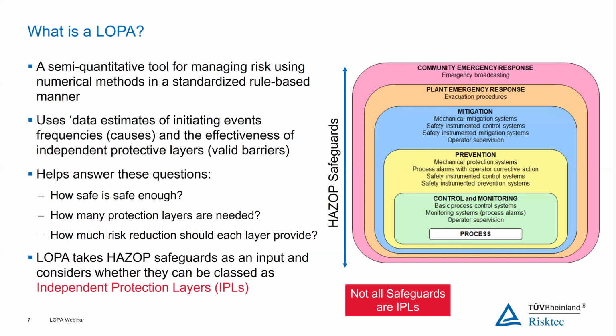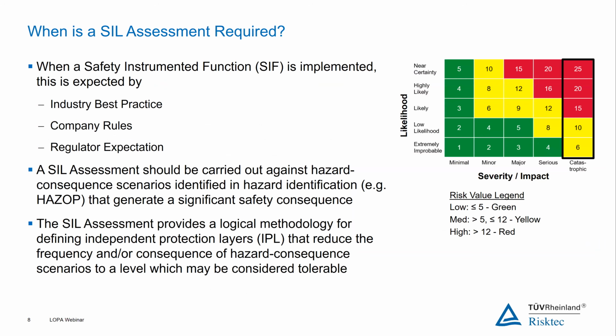So there may be things such as ignition factors for probabilities of ignition in specific areas, occupancy factors to assess the specific likelihood of fatalities or impacts to personnel, again, within specific areas or from specific systems. Even things such as weather modifiers based on prevailing winds and general weather information from the area to incorporate these into the inherent LOPA methodology.